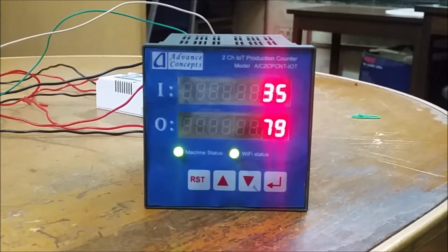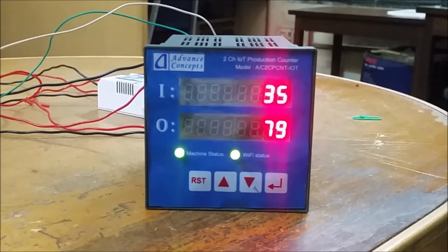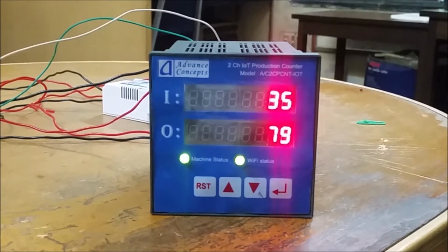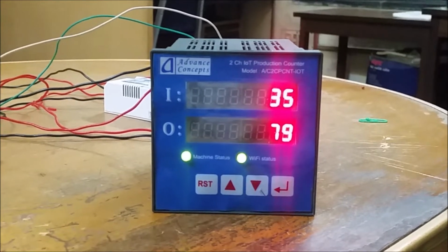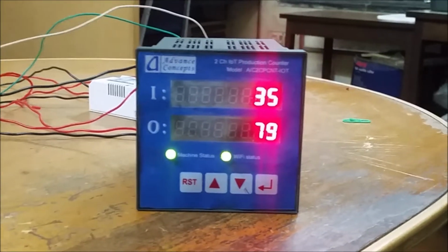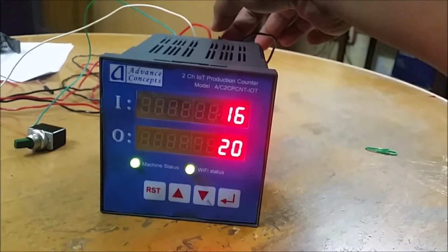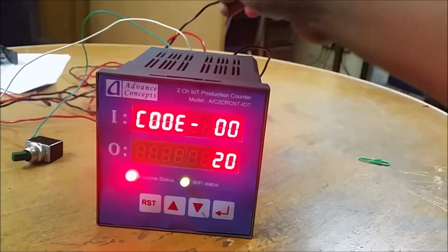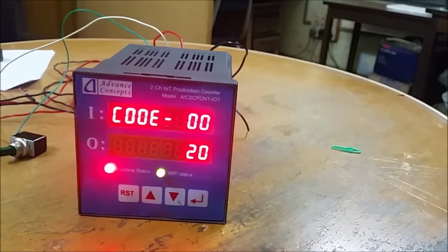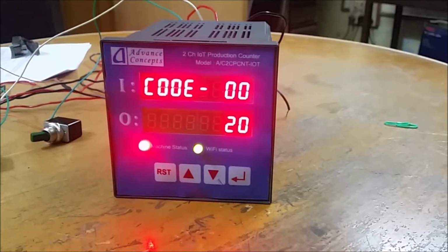So what we've got over here is a membrane keypad at the bottom and two status LEDs above it. The left LED indicates the status of your production machine and even reports to the IoT platform. So when the machine status is high, it shows green, and the moment the machine status is low, which I am simulating by pulling out the 24-volt wire, the LED turns red. It also prompts the user to enter a reason code for the failure. All this data is getting constantly reported to our IoT platform.